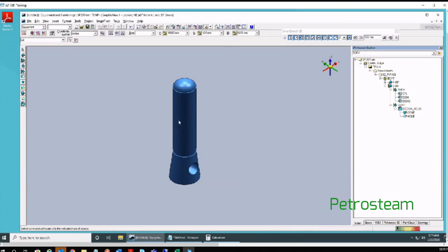When you set All, right now it is selecting only the shape, and once the question mark appears, it will give you other options. But if you want to quickly select only the equipment component, set it to equipment component and select it. Now you have quickly selected the equipment component you need to modify or move.